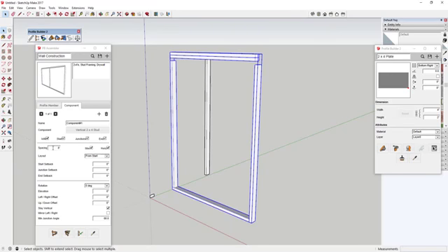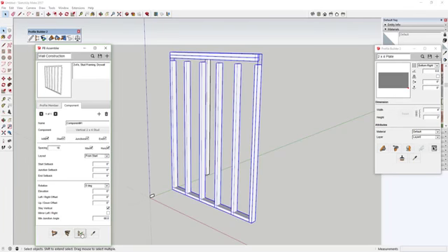So the spacing is basically how much space it puts between your different objects. So you can say you want framing every 18 inches if you want. And then if you click out of that box, it's going to update your object just like this. And we can single click on our object and click apply. And you can see what that does is that spaces these objects at 18 inches along your face. So you can set your spacing in here.